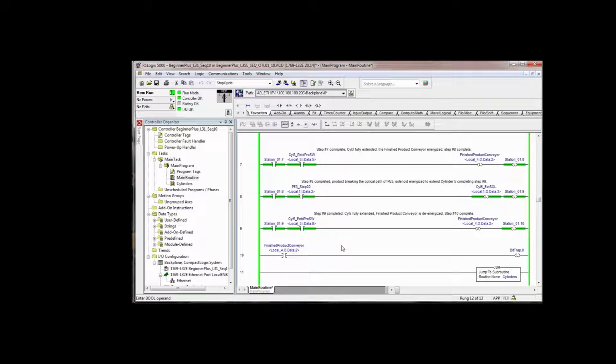And the only reason I'm belaboring this is because you could look at this bit right here showing that it's on and then going right back off. That could strike some confusion and get you to believe that you have some sort of intermittent condition. If you want to say there's an intermittent condition, it is the timing of how the bits in the memory of that controller are being realized on this screen.